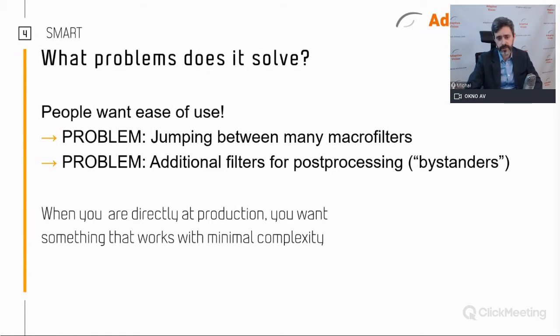Actually, we always thought that creating subprograms is the right thing, but for simple applications where you have very few filters in the program, it actually does more harm than good. And for that, we devised some ways to create an entire program in one view, without macro filters.